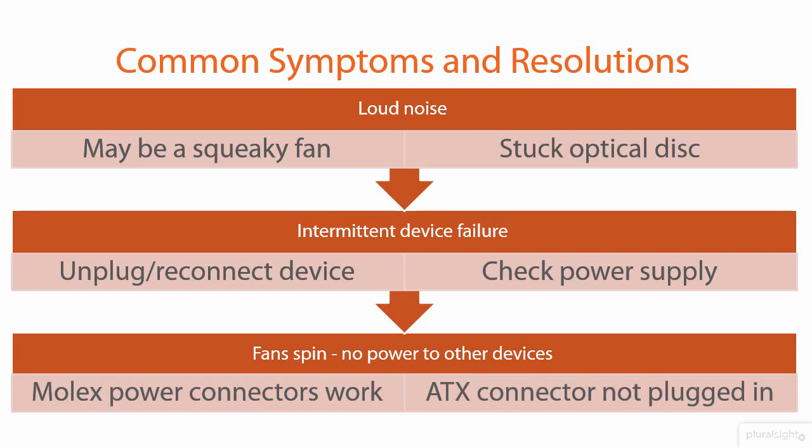Perhaps your ATX connector has come loose or just came unplugged. Admittedly, that's a little far-fetched. Those ATX connectors normally have a hinge, but just understand that it's possible to not have all the power available on the system if you have some plugged in, and in particular the ATX primary motherboard connector unplugged or poorly plugged.